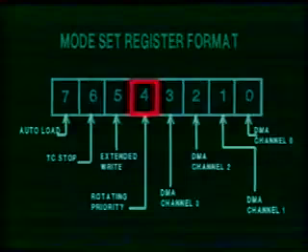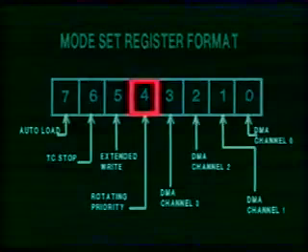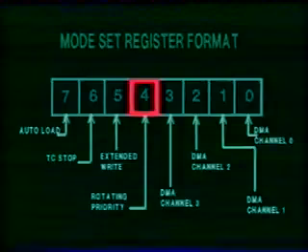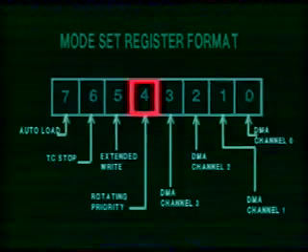Similarly, if at a particular time channel 2 was performing DMA operation and was disabled because the terminal count is 0, the priority, when the rotating priority is enabled, will become channel 3, channel 0, channel 1, channel 2 in that particular order. This rotating priority is enabled by putting a 1 in bit D4, while a bit 0 in that disables the rotating priority.